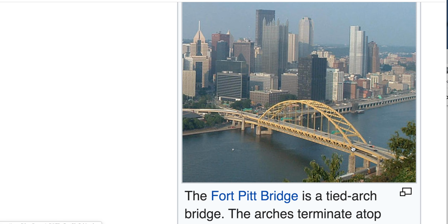You can make a connection into the steel here, making a tied arch system. So as it tries to push out, since it's connected here in steel, it has to try to push the steel here out. It puts a huge amount of compression and a lot of tension in this steel member, trying to push it out as it's connected. Now watch where I go with this.